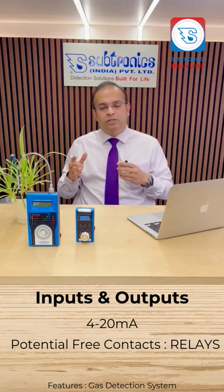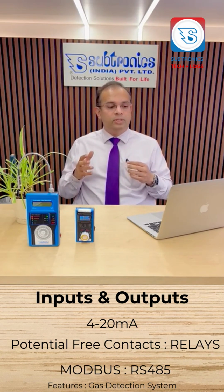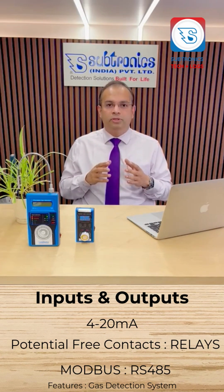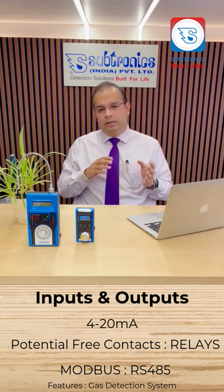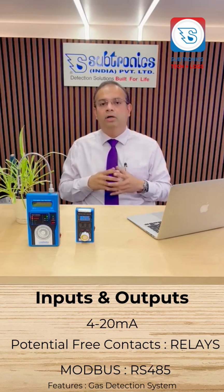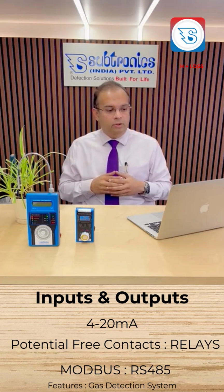Another newer feature is the Modbus output. We would always recommend a Modbus RS485 output. These are digital protocols which interact well with your SCADA, PLC or DCS unit, or an IoT device or a web gateway. So these are the typical features you should be looking out for.